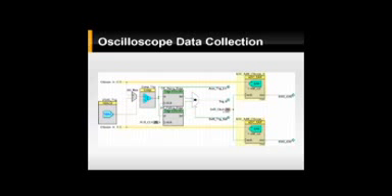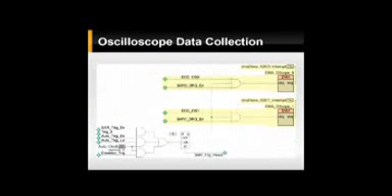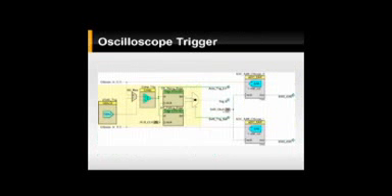Once it's done converting the analog signal into digital data, the ADC produces a pulse, which tells the DMA, or direct memory access, which automatically will retrieve that data and transfer it into memory. The DMA continues to automatically grab data and move it to memory until 2,000 samples are collected, at which point an interrupt occurs, telling the PSOC to send the 2,000 samples to the computer through USB.